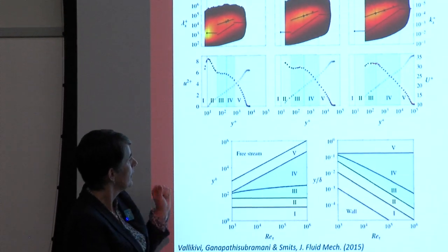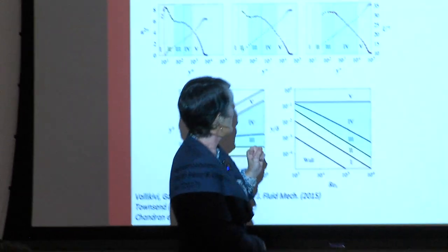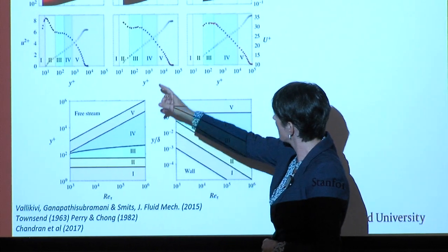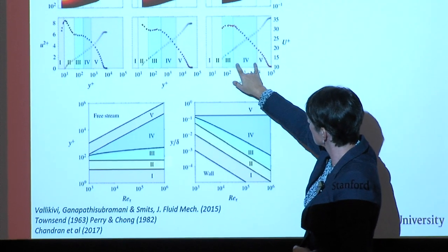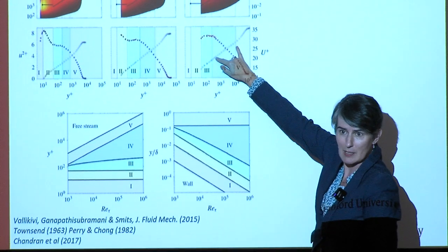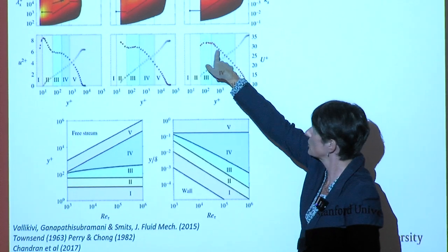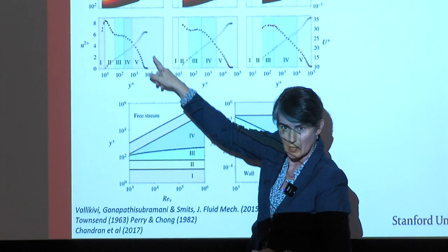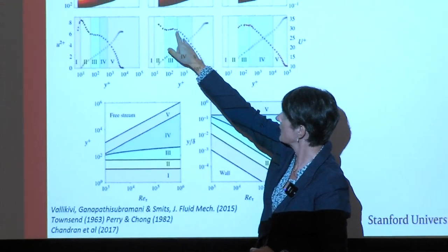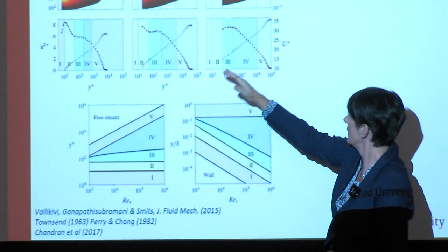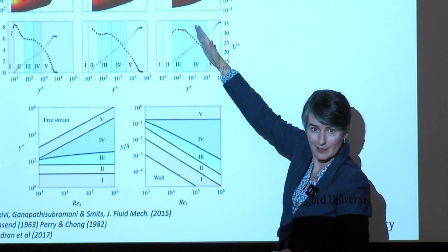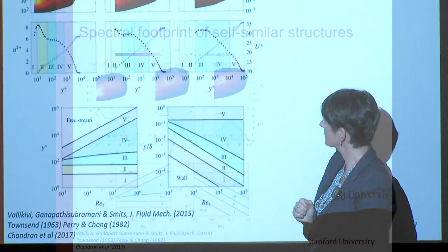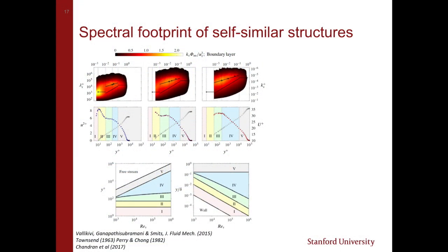So the point of this paper was, well, you can probably see it: as I move to the higher Reynolds number in this blue region, I can see the log in the mean that we've already spoken about, but there's also a log in the variance. Okay, so over here, you can't really see it, the blue curve is bending over. Here you might say, yes, I could probably fit a tangent curve here, but here, very definitely, there's a logarithmic curve in both. And so these authors split up, rather than saying that there was an inner region, a log region, and an outer region.